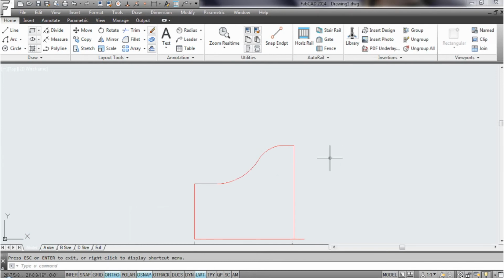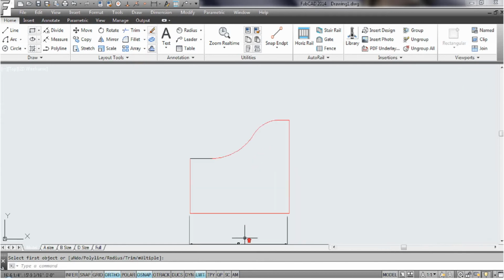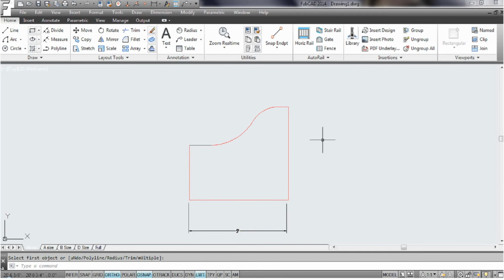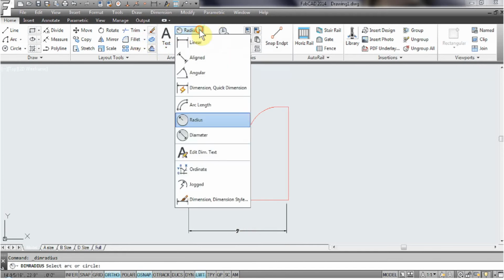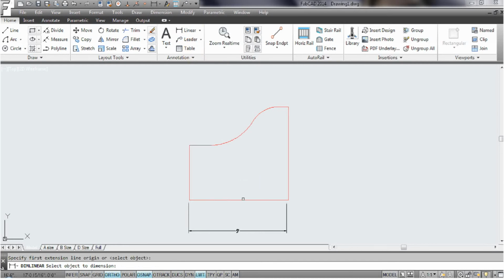The next thing we need to do is clean up the bottom here, so I'll do the fillet command at the bottom. And then let's check. It looks like it's a little bit wider. There's a dimension for the 5 foot, and the gate looks bigger. So let's see exactly how wide that is there. So let's go to linear. All right, it's 5 foot 11/16.